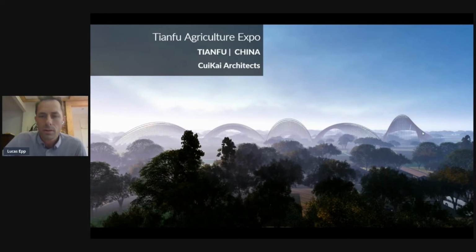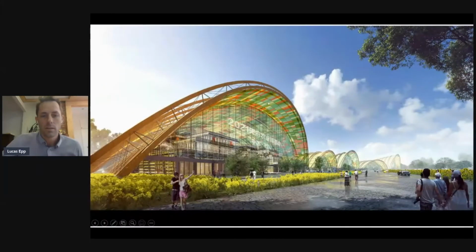Timber vault structures. They're basically arches. And so that makes it, I think, the largest timber structure in all of Asia, and certainly one of the largest in the world at 800,000 square feet. And these 5 vaults clear span up to, for the biggest vault here, about 115 meters. So it's pushing well over 400 feet clear span.